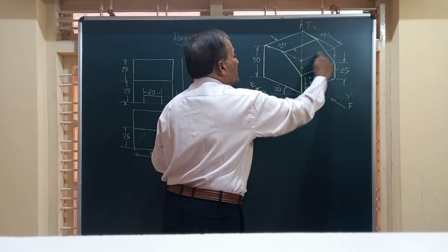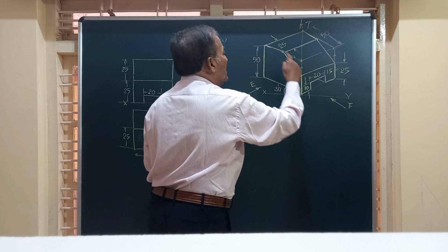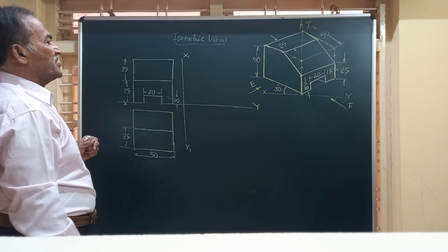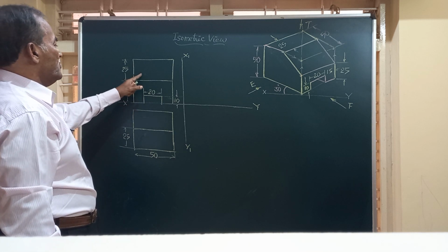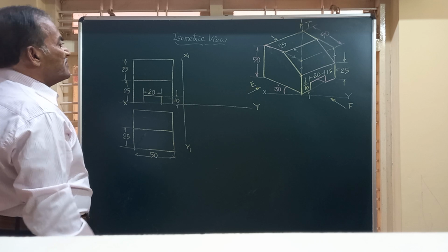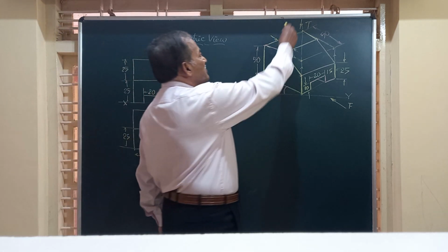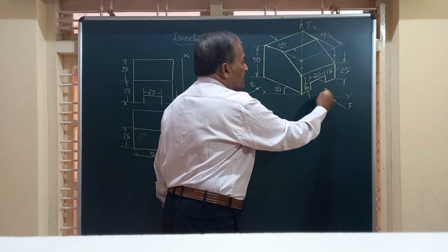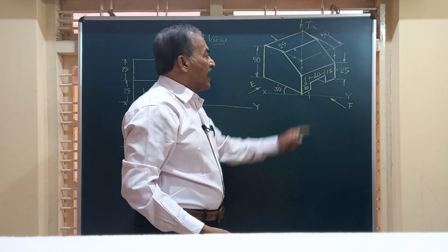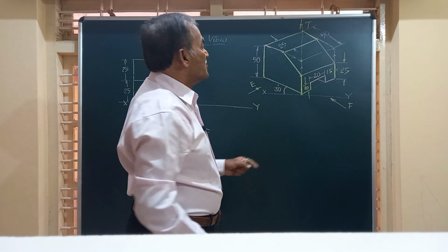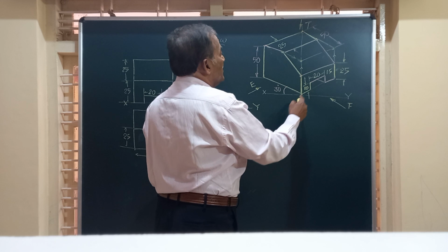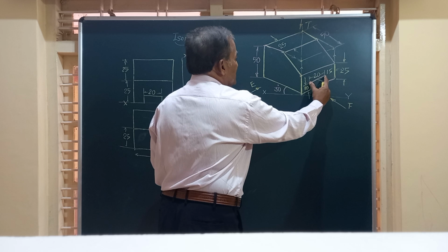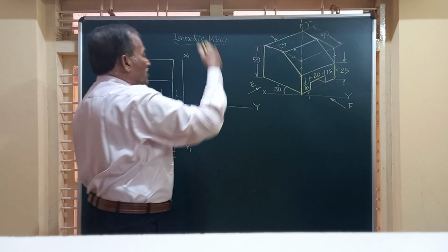Again friends, you are going to see one more rectangle adjacent to that. That rectangle is this rectangle, whatever we have drawn. So you have got the front view, you have got the top view, and friends, you should remember, when you are looking from the top, there is a through slot, a rectangular slot cut at the bottom of the block, and this is not seen. So this has to be shown as a dotted line for this corner passing through these two. Of this width, we have to have a dotted line throughout.